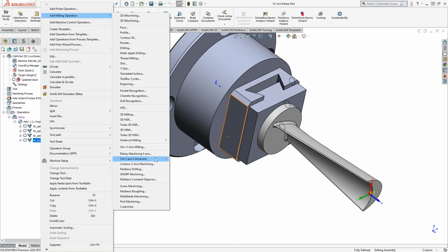Okay, so further down the list, multi-axis drilling, you can kind of do that with the simultaneous 5-axis as well, but this one is actually pretty useful on its own because rather than setting up MAC positions or index positions for each drilled hole, this actually will recognize from your solid the different trajectories of those holes, and then it'll generate one tool path that will angle the drill for each hole. So it's actually pretty useful on its own. But it's included in this list here. We'll touch base on it for a second there.